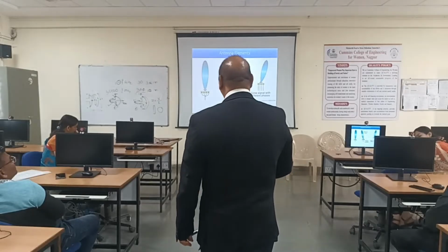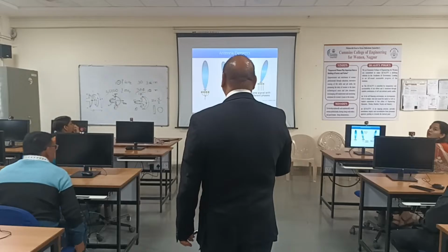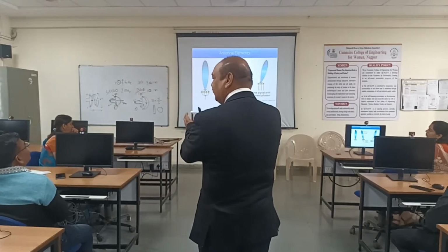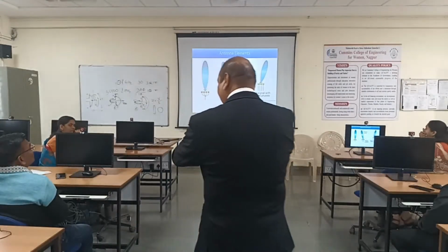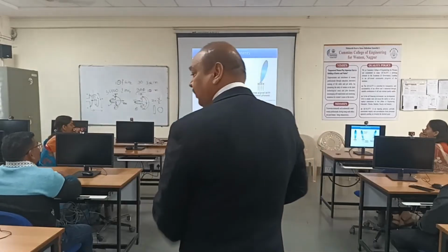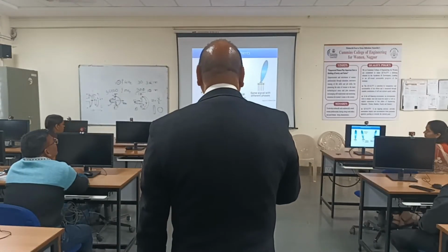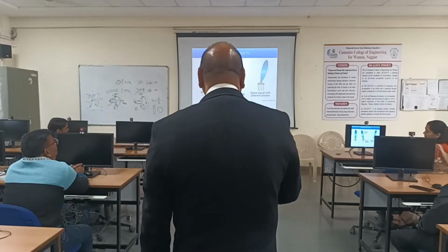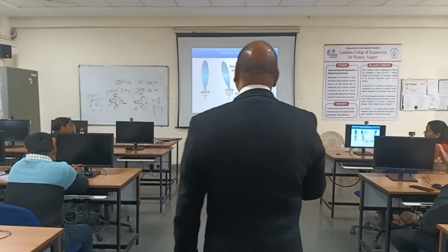To achieve this, we have to use algorithms and a DSP processor. A smart antenna is not smart alone; it is a complete team that makes the beam smart or massive. So this is the same signal. They are different in excitation, and now if you use the phase changer, or we can say phase shifter, here also, it will steer the beam.